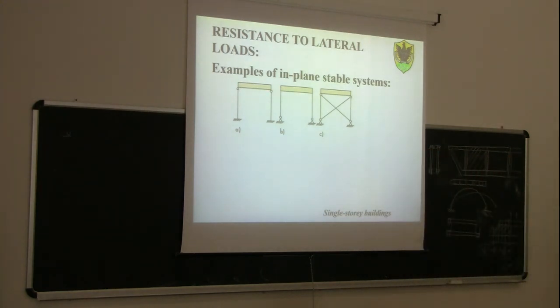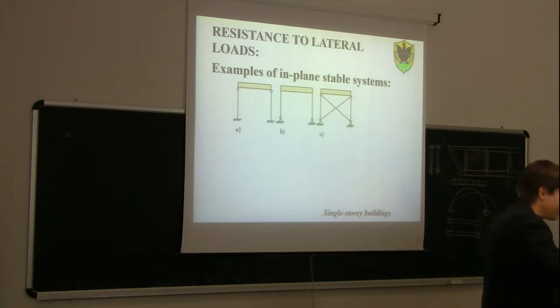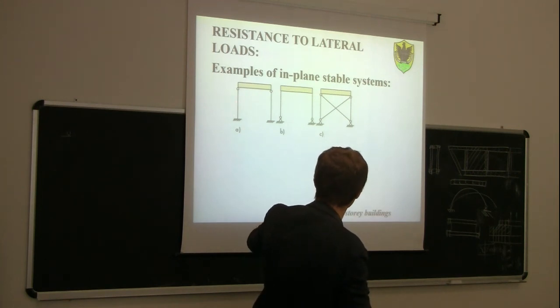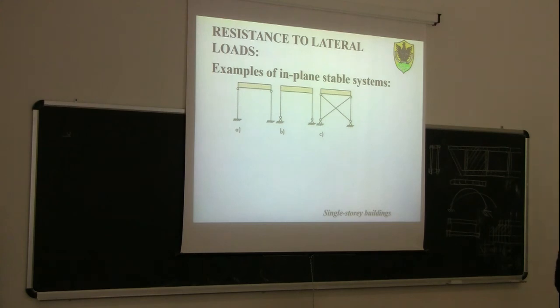For example, this kind of precast building that we had in the Pianura Padana when there was the earthquake had a system like this, more or less, and it was stable. The only problem was that the pin was actually not a real pin, because at least on one side the resistance to shear was simply due to friction, since they were simply supported. So when the earthquake struck after L'Aquila in the Pianura Padana, the beam started moving on the opposite side, the friction was lost, and then simply the beam fell down. Anyway, this is another system that we don't use for timber.